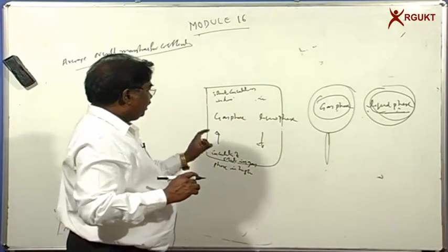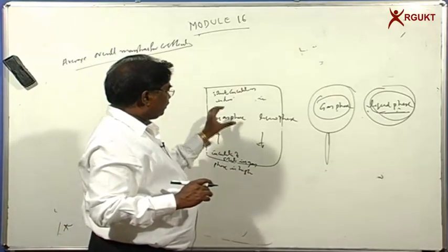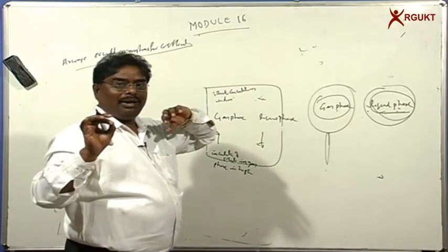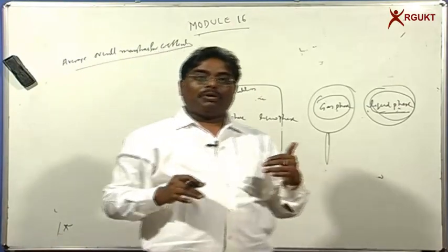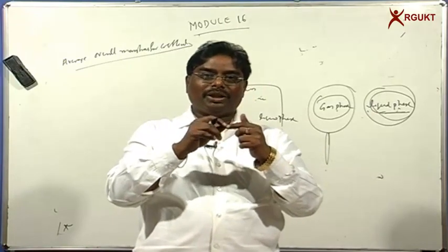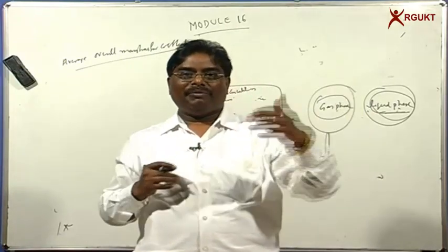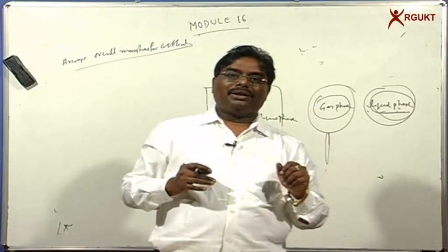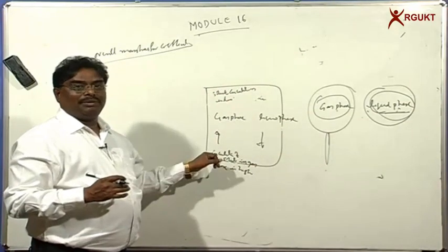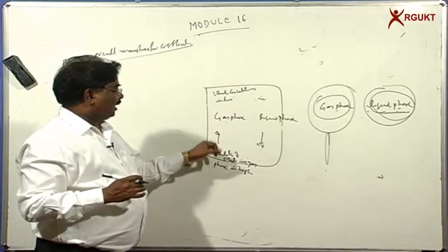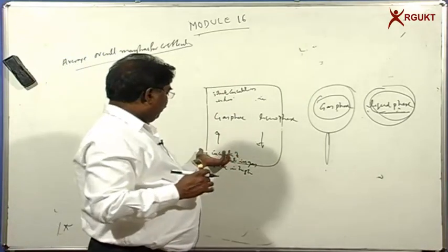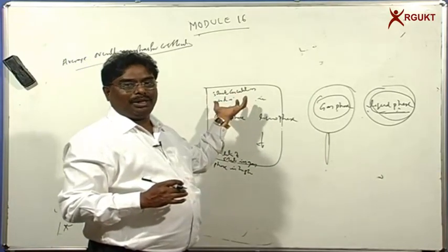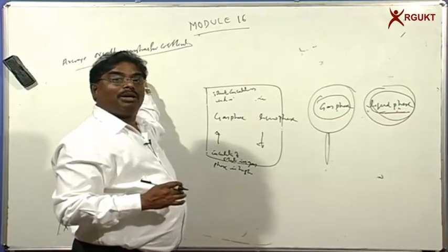So what one can say is that the mass transfer coefficient we discussed previously is the coefficient at a particular location, and we have an infinite number of such locations. So we can take the mass transfer coefficient at location 1, at location 2, maybe an infinite number of points, and we can find the overall mass transfer coefficient for design purposes. But if the concentration changes are not much, we can take the mass transfer coefficient at the bottom, the mass transfer coefficient at the top, and take the average of these two values, and that is what we call the average overall mass transfer coefficient.